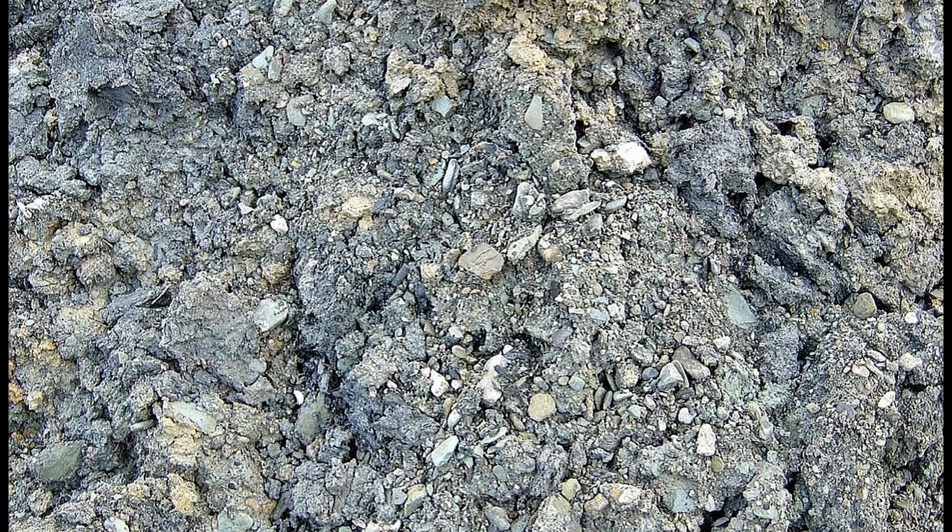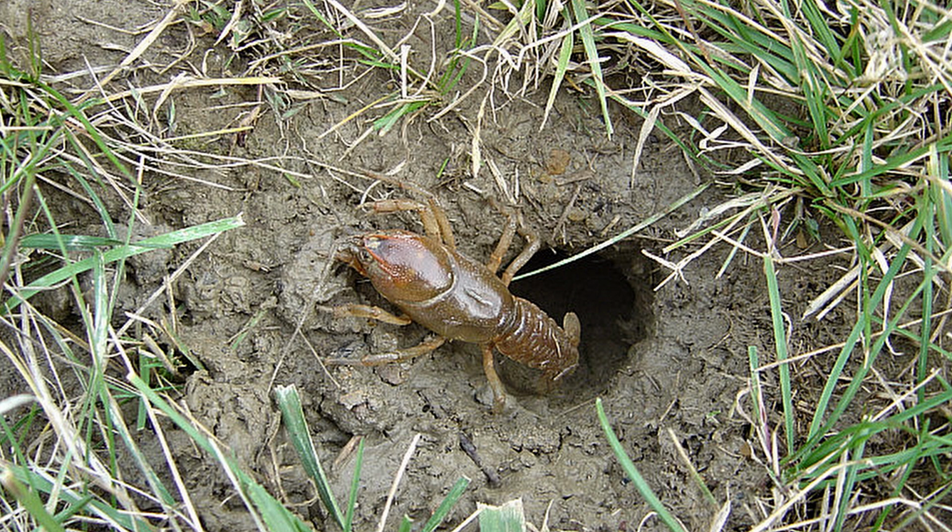It was decided that for the wetland and stream restoration project to be successful, we had to interrupt this gravel layer with a groundwater dam, and the groundwater dam must be based on the shale bedrock. The test hole showed us that the crayfish burrows went down to the groundwater and that the groundwater was flowing in the gravel on top of the shale bedrock.